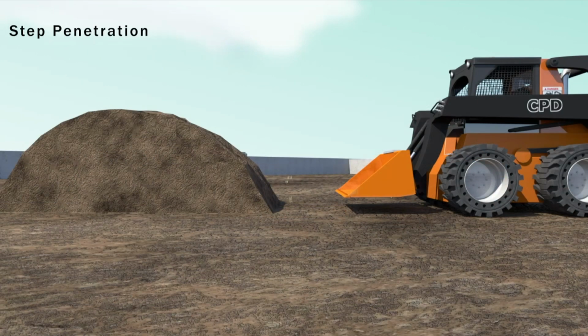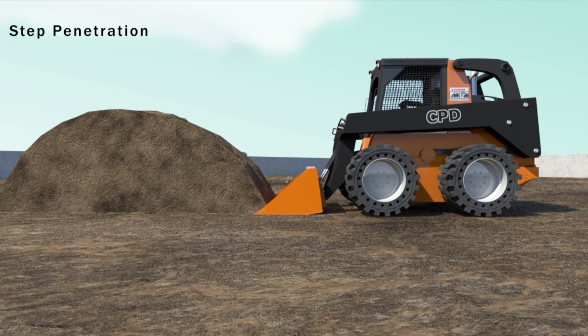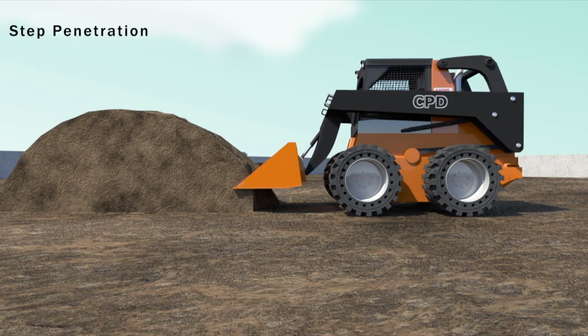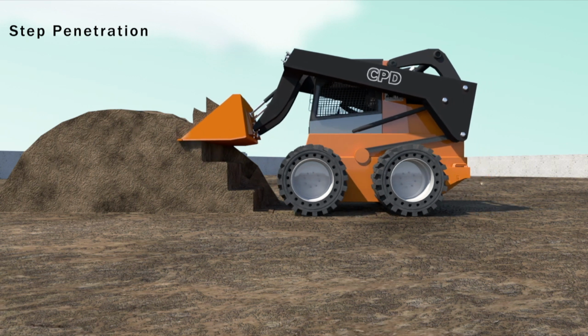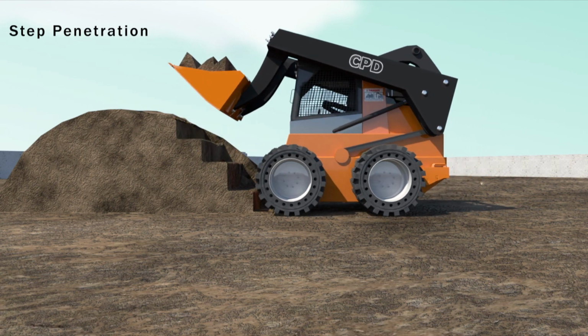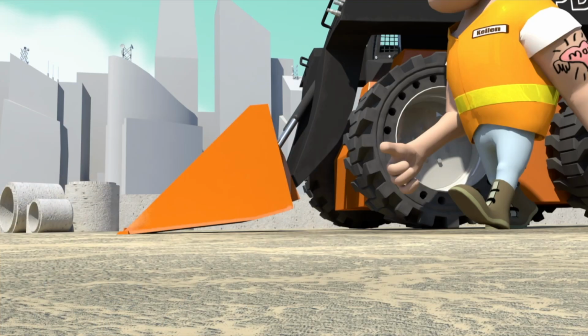Secondly is step penetration, used when material is very dense, wet, or frozen. Place the bucket horizontal at ground level and push into the pile. Raise the bucket about a foot and push into the pile again. Lower bucket to the ground, making sure the front bucket cutting edge is tilted slightly down so it does not create a tripping hazard.